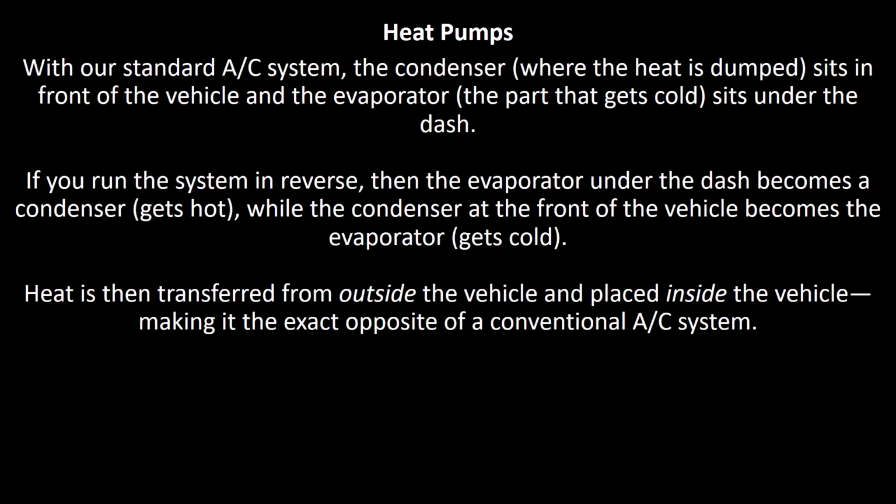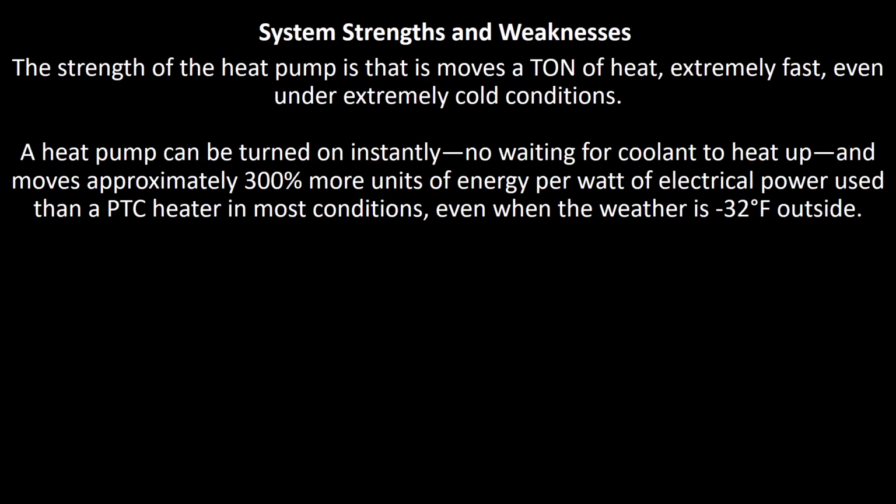It will get hot, while the condenser at the front of the vehicle becomes the evaporator. It will get cold. Heat is then transferred from outside the vehicle and placed inside the vehicle, making it the exact opposite of a conventional AC system. So what are the strengths and weaknesses of this system?